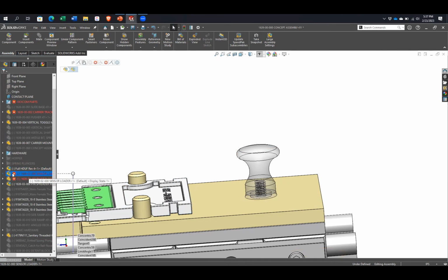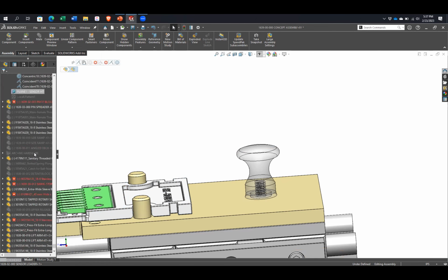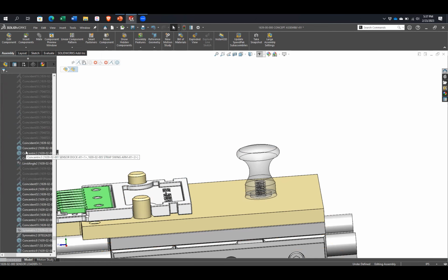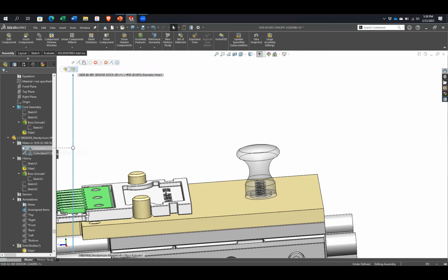And then you have to kind of pre-select it, then hit the asterisk and select it, then it'll kind of fully expand everything. So anyway, point is, if you always are looking to expand a larger feature tree of items, say you've got multiple sub-assemblies stacked up and you're trying to see everything in it, you can expand everything all at once.